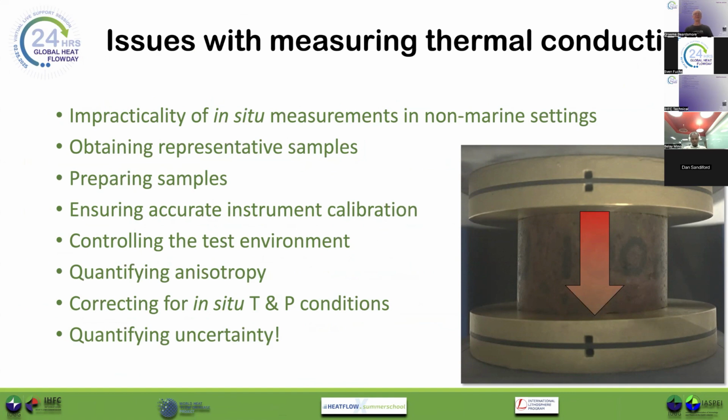But it's very challenging to actually measure thermal conductivity in situ. Even if you have a borehole intersecting the rock, getting a thermal conductivity measuring device into the borehole is far more challenging than just lowering a temperature probe into the borehole. So temperature gradient, relatively easy to get from a borehole. In situ thermal conductivity, very challenging.